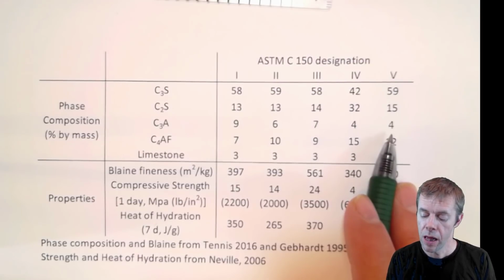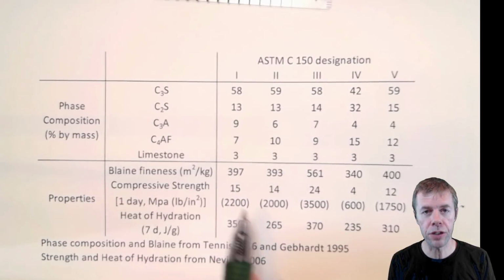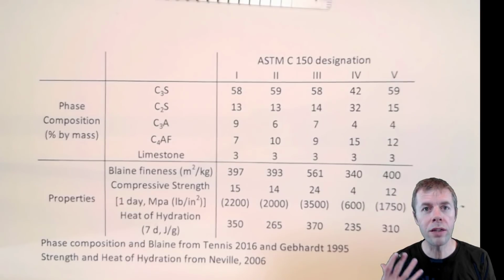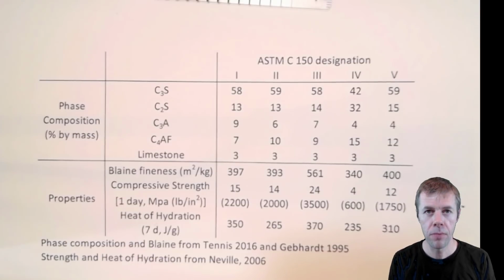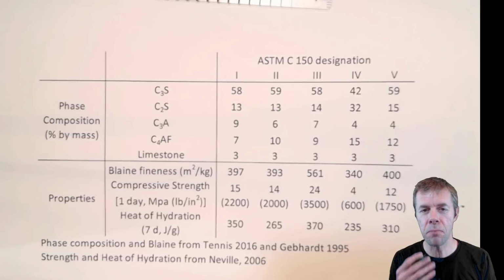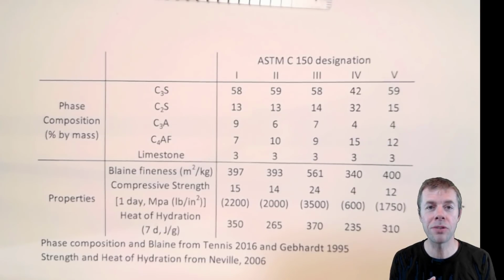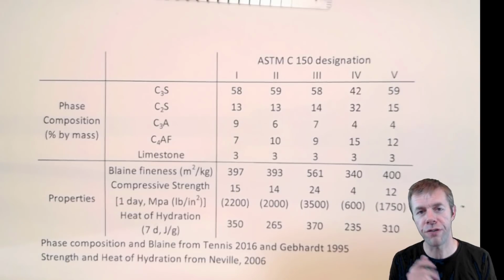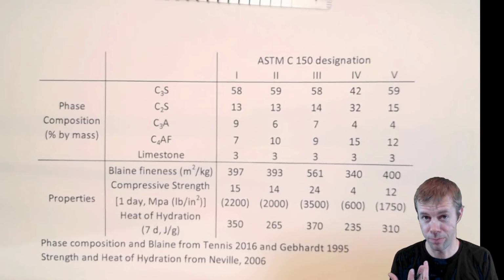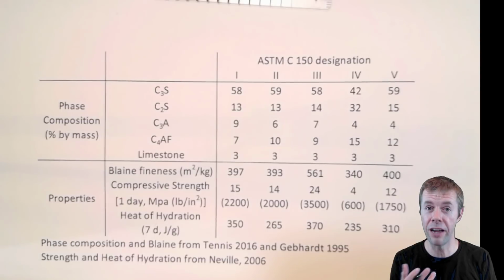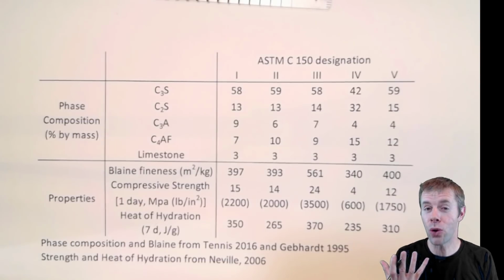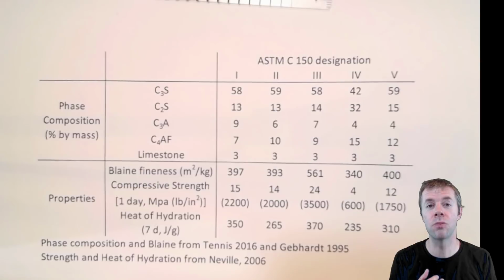It's good. You'll also sometimes see combination cements. Like something's a 1/2, okay? A 1/2 means it meets the specification for a type 1 and a type 2. You'll even sometimes see a 2/5. That means it meets both those, or a 1/2/5 means it meets all three. It's pretty cool when you have one product that meets so many different specifications.